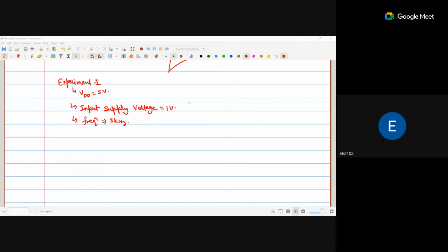Now if you go with this circuit, you can see R1 and C1. C1 is used as a feedback and R1 is the input signal, and VCM is applied at the positive terminal. On the basis of this, can you calculate the equation of that ramp signal? Calculate this ramp signal equation and compare it with equation number 1. So you will get the component values.